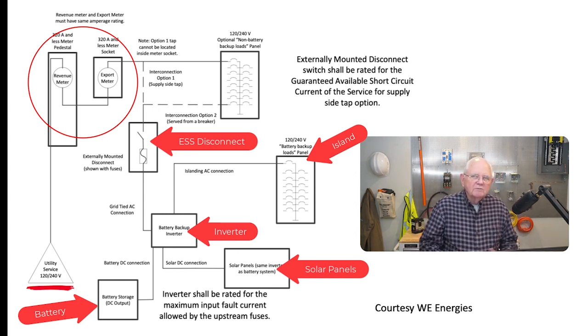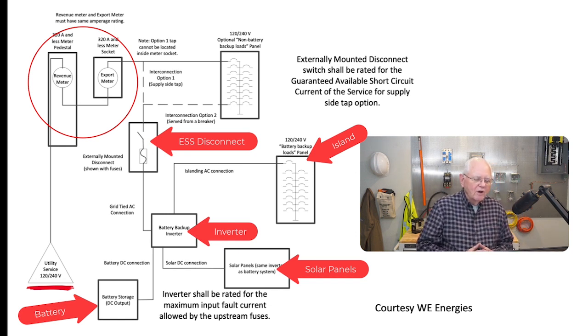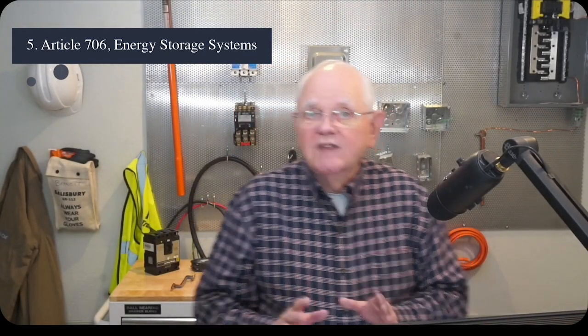All these components must be listed. The energy storage system, we're going to see in Article 706, is required to be listed, and it's required to have a nameplate on it. That nameplate is going to be important to us because we can pull information off of it to do things like size conductors and determine the ampacity requirements for the conductors that we need, and so on. The next topic, let's jump into Article 706 itself and go through some of the highlights.